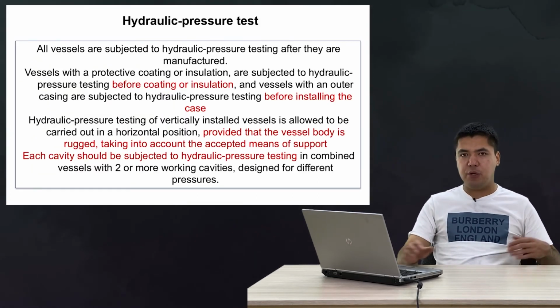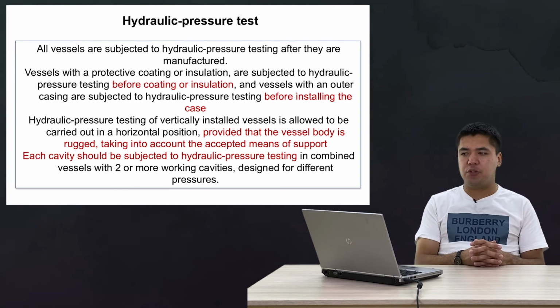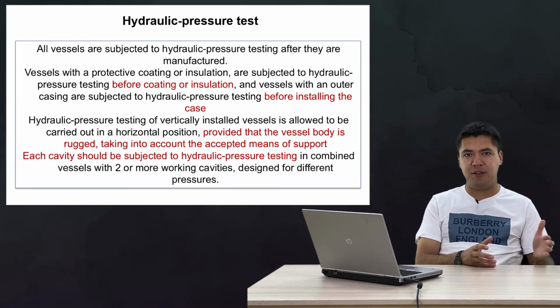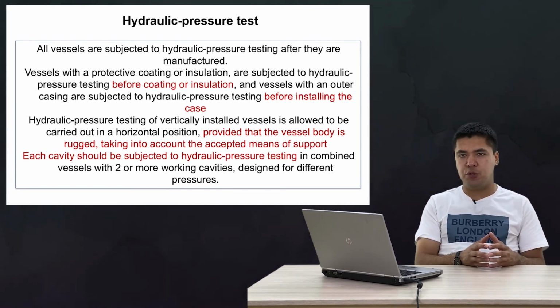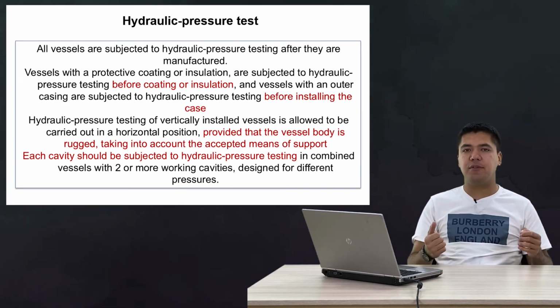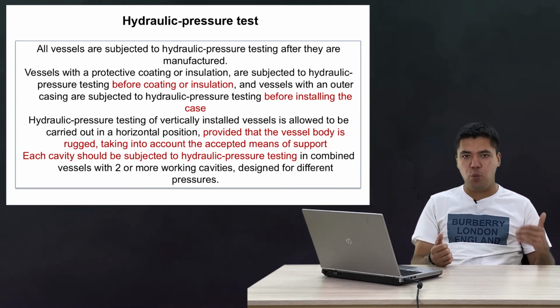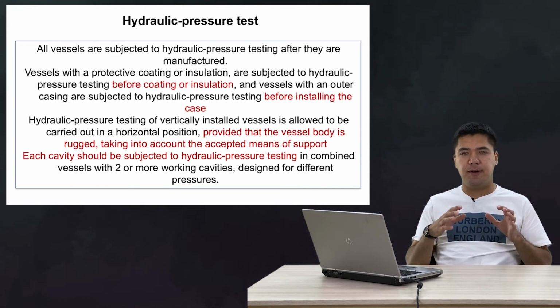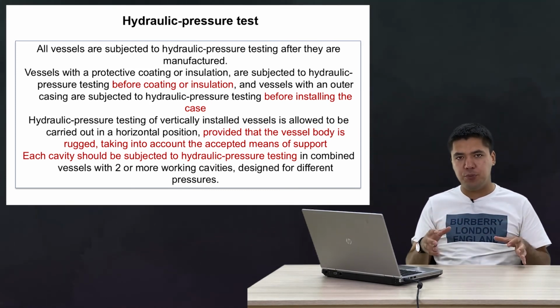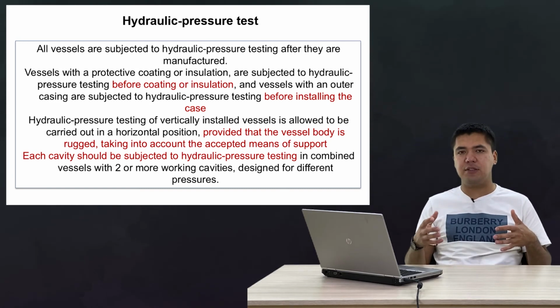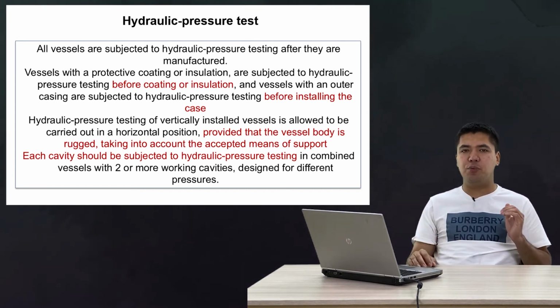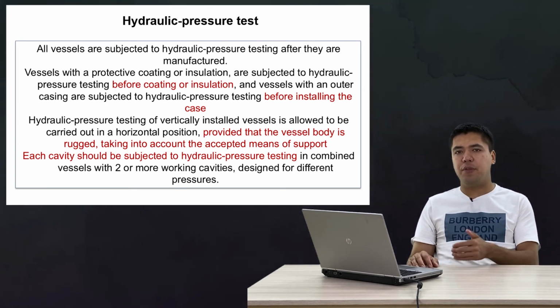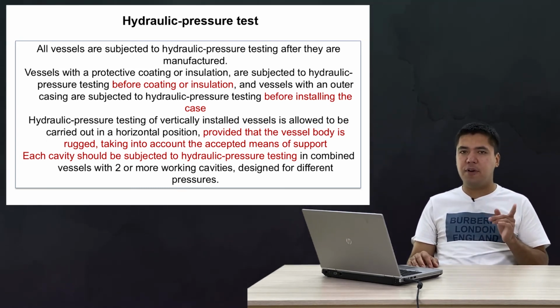And the next, as a part of the technical inspection, we call the hydraulic pressure test. So from the name, it is very obvious. Here, water is used in order to check the strength level of pressure vessels. Water pressure is applied to the tubes, system, pipelines, and vessels, and that water pressure will exceed the normal working pressure level of that device, for no longer than 5 minutes.